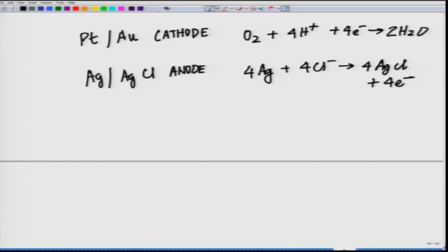A Clark's electrode is calibrated by placing it in a solution of known oxygen concentration, and a graph of current versus oxygen is constructed. So, basically, based on the oxygen concentration, your current is going to change.